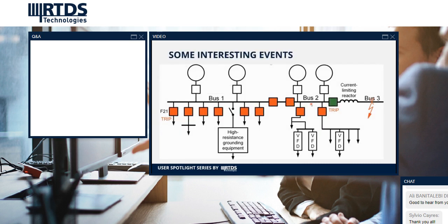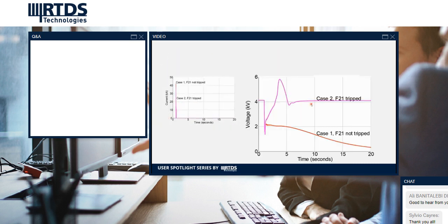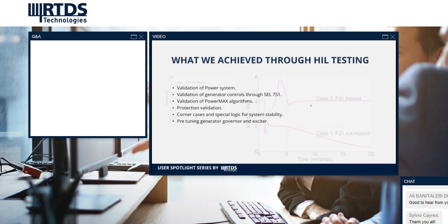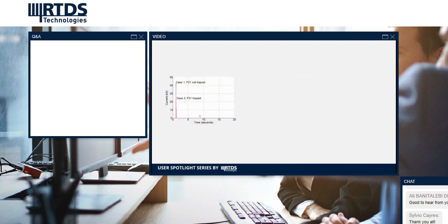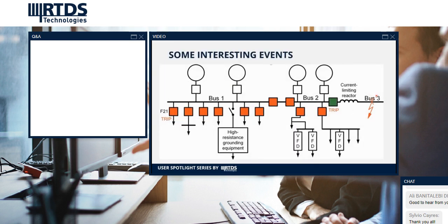So going back, I did not show that here. But they used a GOOSE command when the protection would detect a 3-phase fault. It would send a GOOSE-based command all the way to the feeder, because it was one system when it comes to comms.